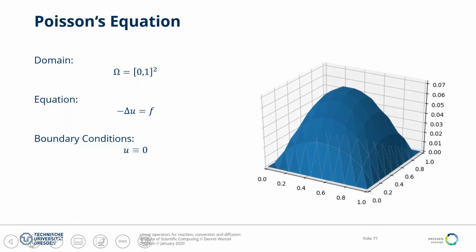And that gives you this. So having implemented this assembly process that we have just talked about, you get this as a result. So you compute your stiffness matrix, you compute your load vector, you solve this whole system, and then you plot this dof vector. Then this gives you this. This is not very spectacular, but it reflects the kind of behavior that you would get if you take a membrane and push from below onto the membrane.